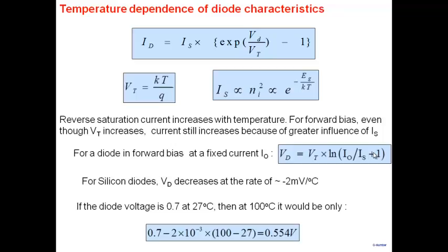So what happens is, note that your ambient temperature may be 50 degrees Celsius, let's say. The diode junction temperature could reach 75, 100 degrees Celsius. Because what is happening is, when you're forward biasing the diode, you're passing a lot of current. Okay? Note that there is a certain amount of voltage across the diode. So if you're passing, let's say, 1 ampere of forward current, just a hypothetical case, and the voltage across the diode is 0.7 volt, the power which is being dissipated at this particular place is 0.7 watt. That's a lot of power, a lot of heat being generated.